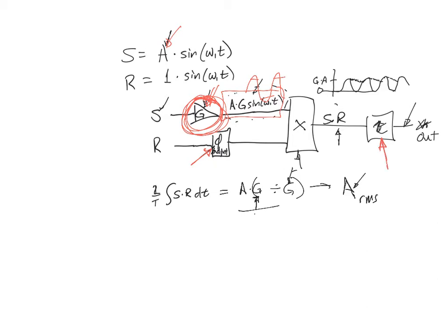The time constant right here is the thing that sets how much this output will sag before the next peak comes along. If you have a wave coming in that has a period, I'm just going to pick a period here, of 1 second. Let's say that was the period of the sine wave there. Well, because this is sine squared, that's like sine 2 theta, this is now the 1 second. So this piece right here is only a half a second. You don't want this to sag away very fast here. In other words, you want a time constant that is long compared to a half second.